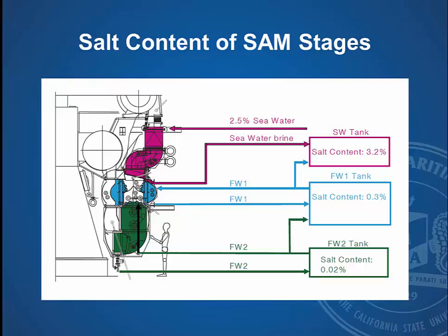The interesting part about this, though, is the salt water, not only are you spraying it in, but it's atomizing, right? It's turning into vapor. So you actually have a little bit of freshwater production, and your freshwater tanks will actually increase, and some of that is drained over the side. So what is being pulled through as humidity is pure water, right? You're not pulling salt water down. The salt water is evaporating and leaving a brine, and then that water goes through the two freshwater stages to make sure that you're not going to have any salt being entrained and carried into the engine.